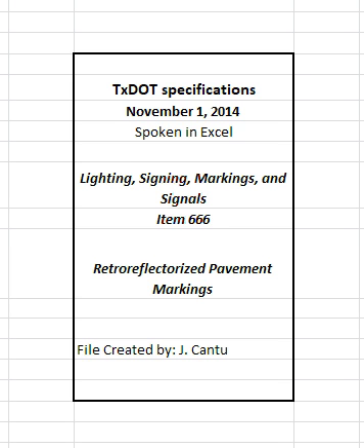Work zone pavement markings, Type II, paint and beads, used as a sealer for Type I markings, thermoplastic, will be paid for under Item 662, Work Zone Pavement Markings. If the engineer requires that markings be placed in inclement weather, repair or replacement of markings damaged by the inclement weather will be paid for in addition to the original plans quantity.